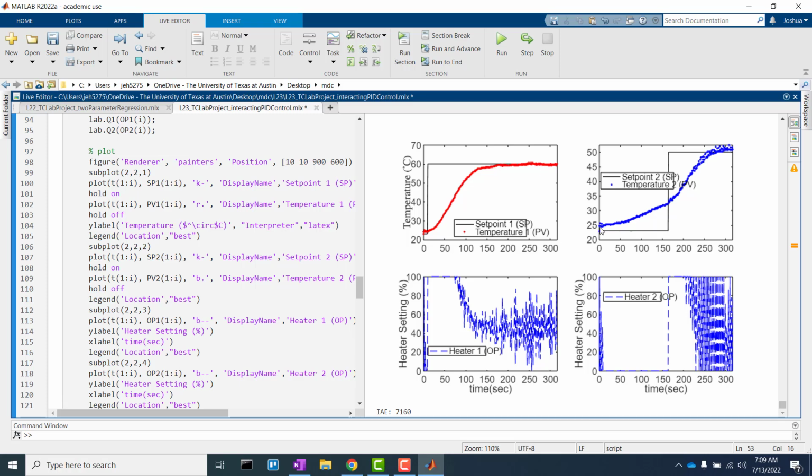And then our heater 2 starts off a little bit higher than we'd like, and so because of that we'll have some jitters as it tries to go down, and that derivative control causes it to kick up once or twice. Nonetheless, it comes up and you can see it's kind of like a bimodal distribution where it starts to scatter a little bit and have 2 different temperature readings.